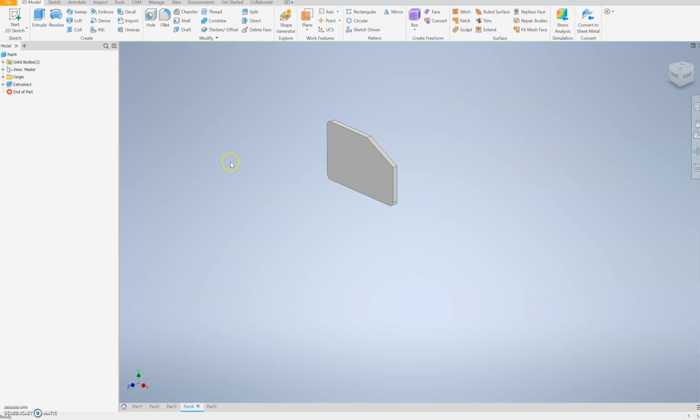The last thing that you would do with work planes is an offset one. This is actually probably the most common reason to use these. Let's say I'm designing this bracket here, and I need another one on the edge. There's not really a way to do that with spacing. So what I can do is click on the plane button, click on this surface, and if I click and hold and drag, it will allow me to set a plane offset.